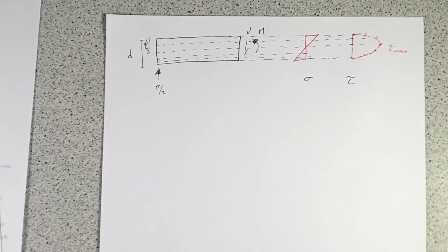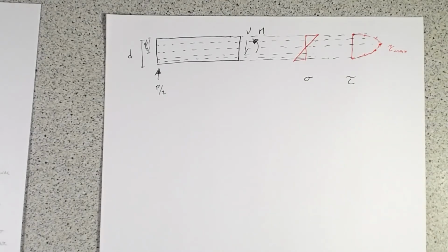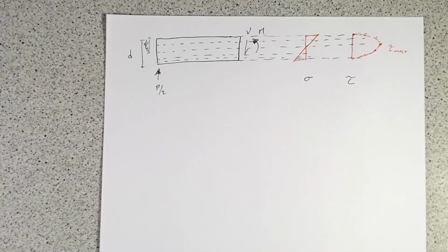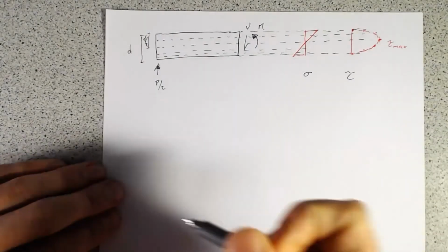And we will find out in the next lesson that it actually goes as a parabola. But you can see just simply from, no numbers, nothing at all, just from free body diagrams and equilibrium, we now have some intuitive sense of how shear stress varies along a rectangular section. And it's got to follow some rules.